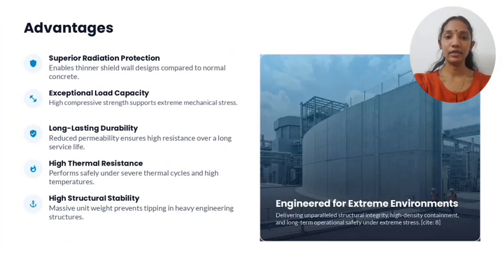Next, heavyweight concrete offers many advantages. It provides excellent radiation protection, allowing thinner shielding walls. It has high load bearing capacity because of its high compressive strength. Its low permeability gives it long lasting durability.